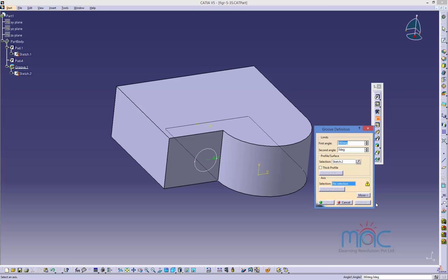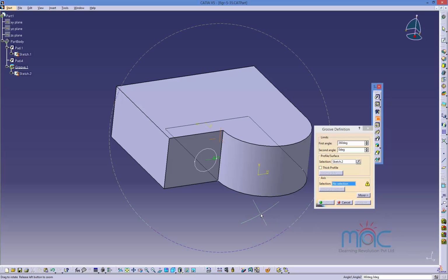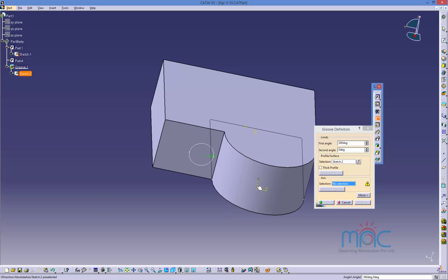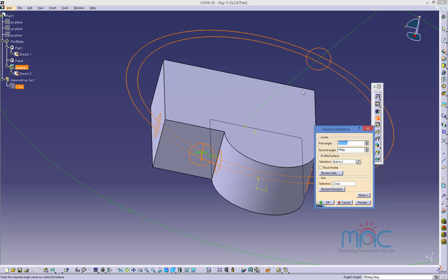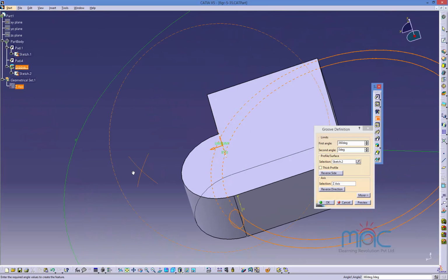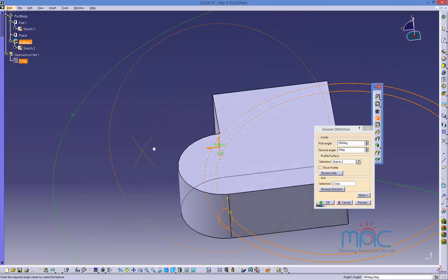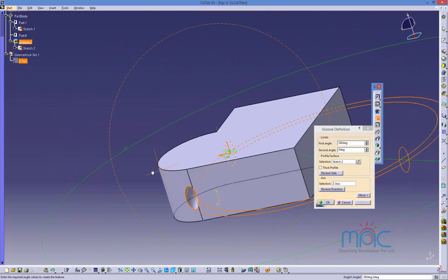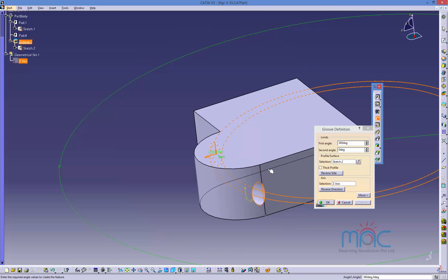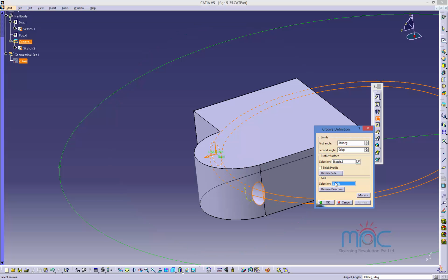And if I choose the Z axis, with respect to which one will it take? With respect to this center point, it will take the sketch center. And if I go to the Z axis, what happened is it is rotating through which center point. That is very, very important. So where is your Z? And if you go to the preview, it is cutting it, but I'm getting some abrupt output. So how do I fix it? So it's better in that case to have a sketch axis.